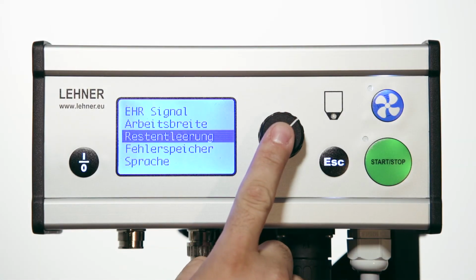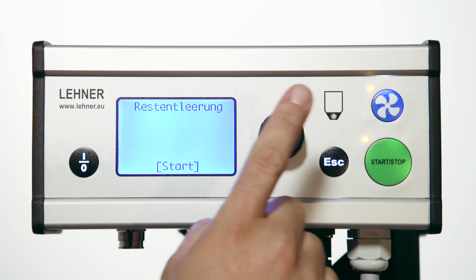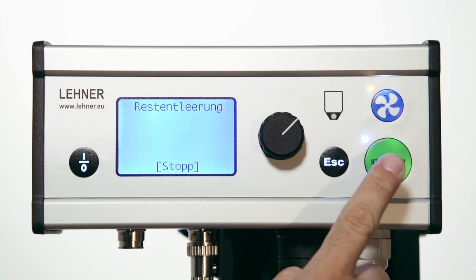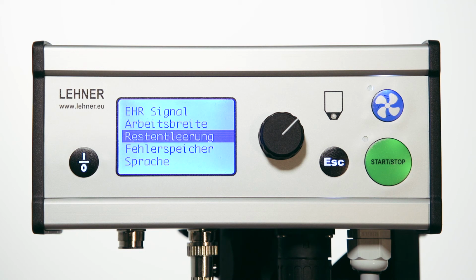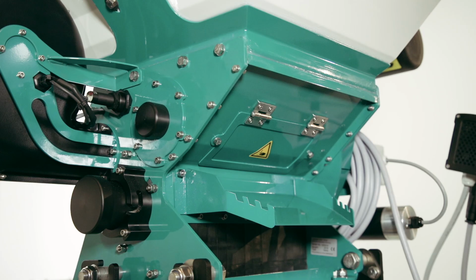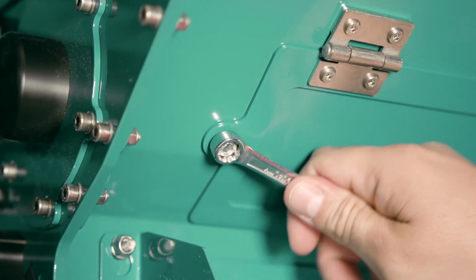There are 2 ways of emptying the hopper. The first is to do so electronically via the residual discharge menu and the Start-Stop button on the control panel. Here, the seeds are discharged via the hose outlet. This allows you to fill the residual seeds in the calibration bag and use them again later. The rotary feeder shaft has a set speed for residual discharge to ensure fast emptying. Alternatively, you can empty the hopper via the residual discharge hatch on the spreader.